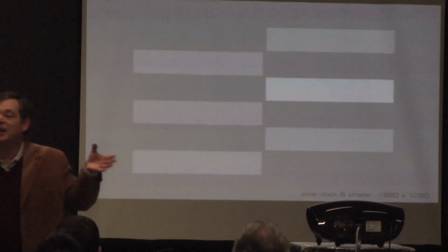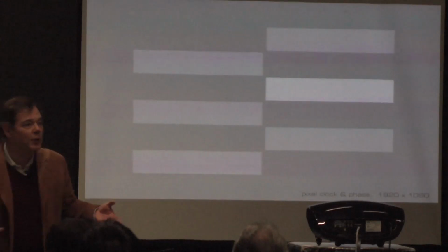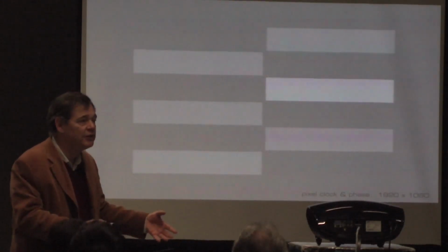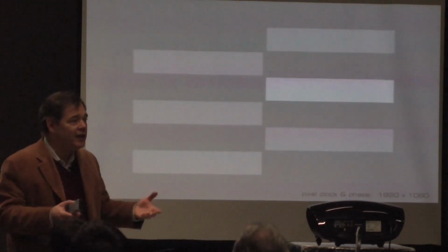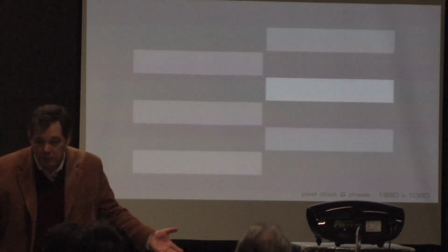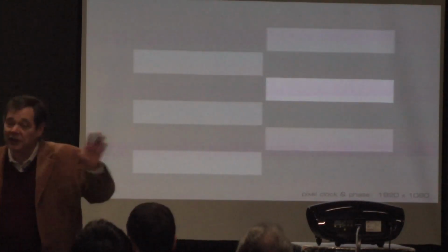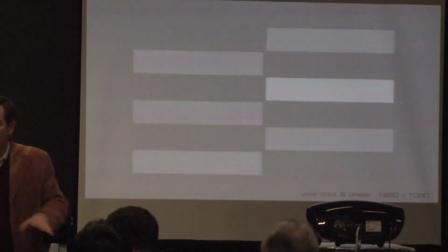They would not be words you would ever choose to get a 1080p display. So here again, this is part of evaluating the 2D capability of the set first. Because if it can't reproduce a 1080p 2D signal, there's no way it's going to reproduce a 1080p 3D signal. So we have to check. This is a step-by-step approach. Make sure it can do 2D first.